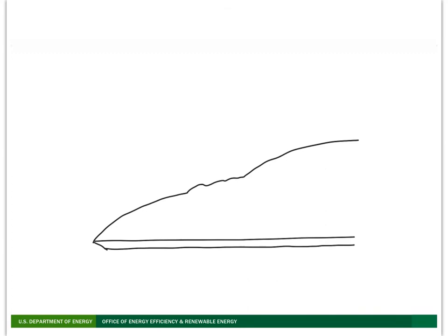If we go back to the example where we had been thinking about the different flow regions, we started out with laminar, we went through some sort of transition, and we eventually ended up in turbulent. The heat transfer coefficient changes as these different velocity and flow characteristics change. And of course, as I mentioned, this is the boundary layer. So we can add to this graph the transitions that occur with the heat transfer coefficient.